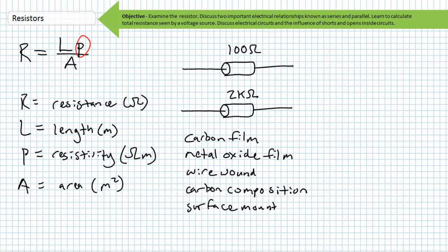Most likely, you'll deal with carbon film resistors, and sometimes metal oxide film or wire wound resistors for higher power applications. Carbon film resistors are your typical brownish tan dumbbell looking resistor, and these are the ones you'll most likely use in a basic electronics lab. Pretty much the same thing can be said about the external view of a metal oxide film resistor, except they're not beige, but rather the shade of powder blue I'd normally find nauseating, but since it's associated with higher power ratings, I've grown somewhat tolerant of it.